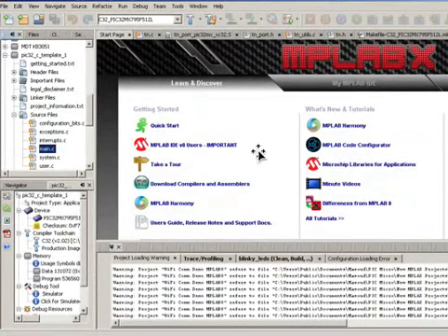Once you've done it, for example in here I just created a PIC32 C template 1. This is the project, so it will automatically create all these folders in here. If you look at this one, these are the header files. The header files for C are .h, in order to simplify the program, but the main thing you are interested in is source files.